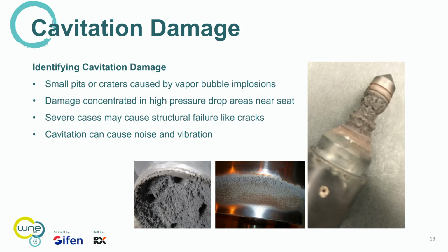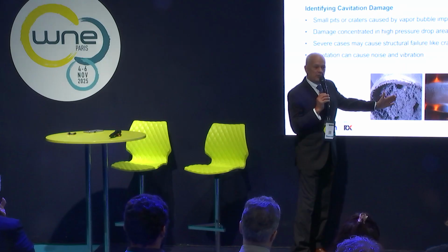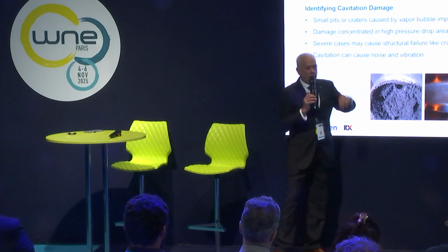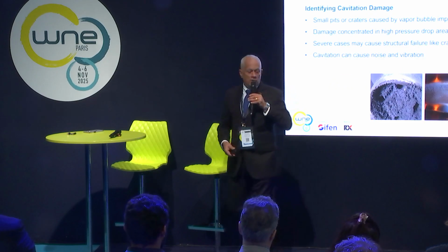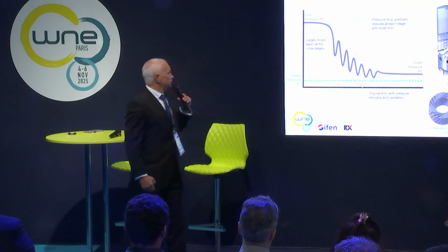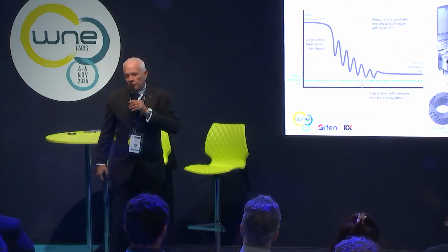it, okay? If you look, it's interesting because when I have a valve problem in the field or somebody comes, I can typically tell by looking at the trim. If you look at this trim, this is the implosions of those bubbles, so you can see it's a very rough surface from where that cavitation impinged on that trim. Okay? So, how do you solve this?